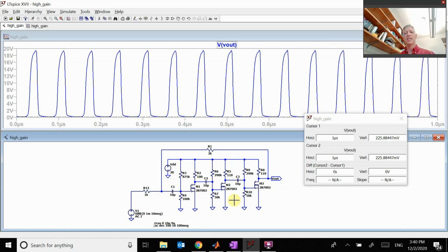It's actually now a non-inverting, or it has positive feedback instead of negative feedback. So that means I took this 2 millivolt signal and then I amplified it, and then I took this signal and added it. So now I'm going to take the output, add it to the input, and amplify it and amplify it and amplify it. So each time I go around this cycle, it gets bigger and bigger until it basically just saturates. And so we get this whole signal.